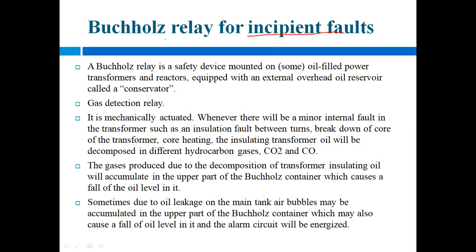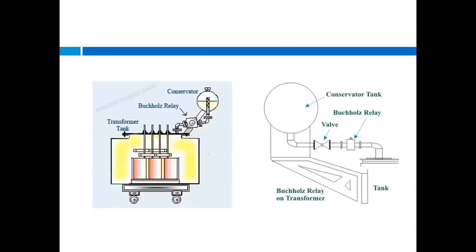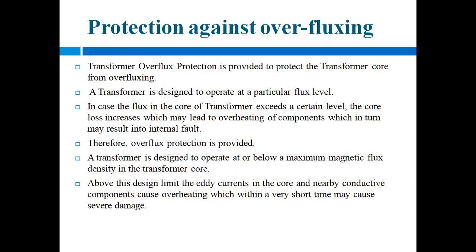So this Buchholz relay is connected in between your transformer tank and the conservator. Here this is the transformer tank, Buchholz relay is there, conservator is there. So if any fault occurs, it will produce the gases, and these gases will actuate this Buchholz relay.